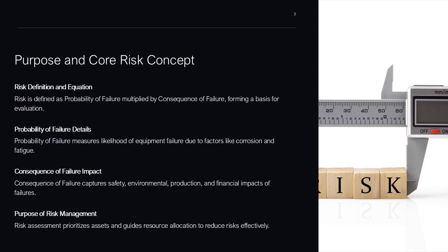At its core, risk is defined as the combination of the probability of failure, POF, and the consequence of failure, COF, commonly expressed through the simple but powerful equation, risk equals POF times COF. While the equation itself appears straightforward, the rigor lies in how each component is determined, validated, and interpreted.